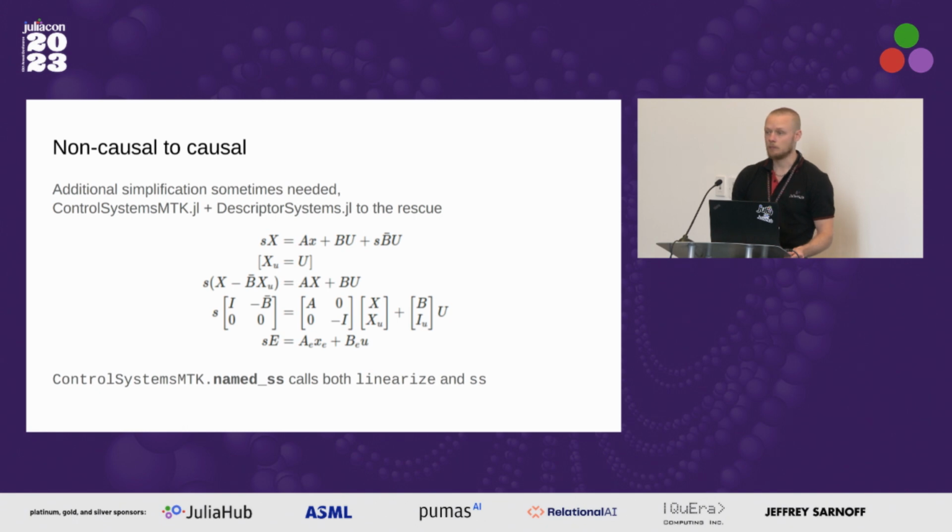Sometimes ModelingToolkit will fail to spot certain patterns in the simplification, and then you actually end up with a non-causal system, even though you expect a causal system. So a non-causal system in this context is a system that performs differentiation of the input. And we typically don't want that.